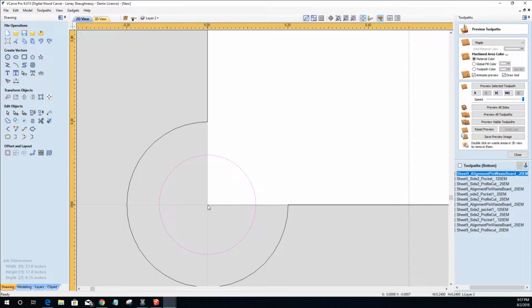If you want to be dead nut sure that you're right there on that corner, there's a lot of ways that you can do that. One is use something like the DWC quick set jig, right? Because it finds that bottom left corner. Or two, get a V bit and put the point of that bit right on that corner, and zero out your X and Y, and that's XY0. Doesn't matter if it's a V bit, a 1/4 inch end mill, or a 1/2 inch end mill, because the center of the bit is the center of the bit, no matter what.